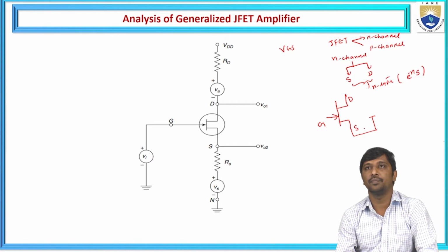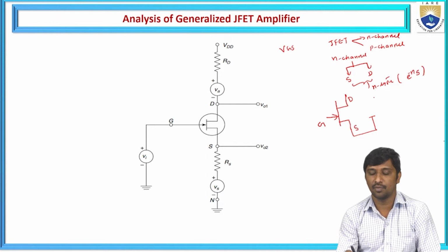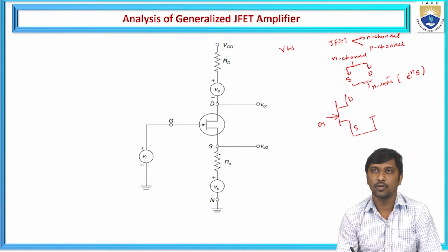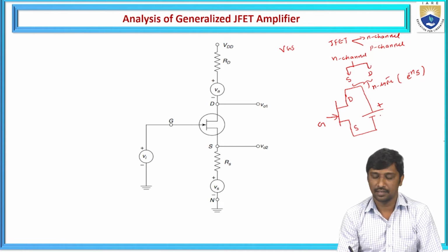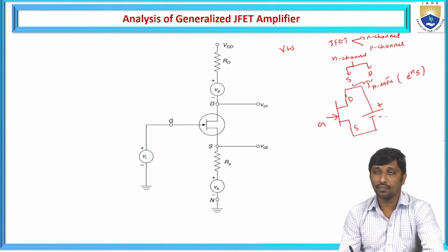Why is it connected to the negative pole? Because the source and the drain are made up of N-type material, the majority charge carriers are electrons. For these electrons, we apply a negative potential with respect to the drain. Hence, the drain is biased with the positive pole of the external battery, and the source is biased with the negative pole of the battery.